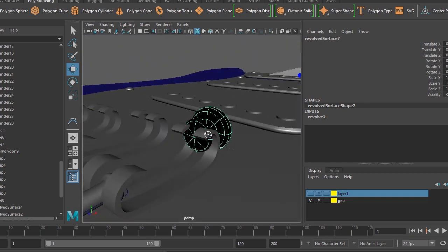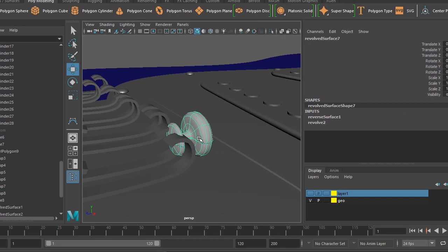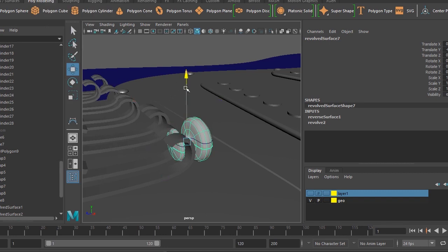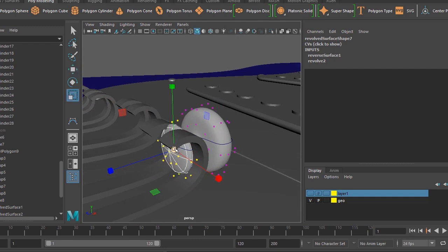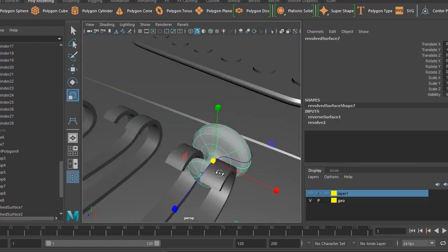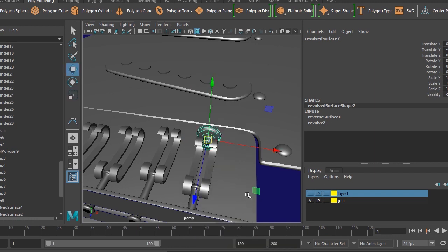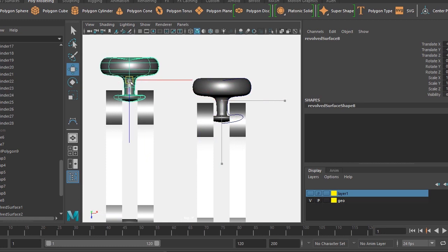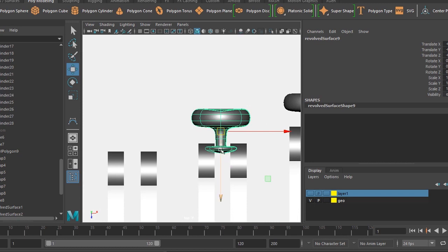Black color means it is having a reverse normal issue, and then I'm going to choose modify center pivot, and then just move it down a little bit, and then I'm going to scale this. Assign existing material blend, then I'll be putting that. Control D.